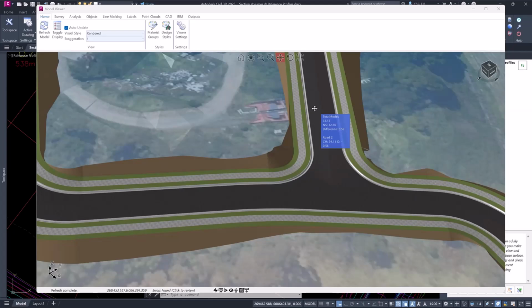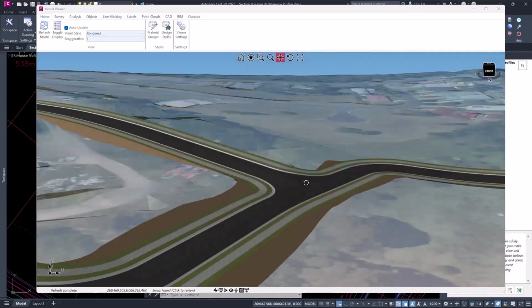So it's really good for that idea of the intersections because we can actually lock up the regions here where the road is running pretty straight, but unlock this region in here where the curb return kicks in so that I can manually grade that part of the world to try and resolve the potential design flaws that I've got in my job. So let me show you the flaw that I introduced into this.